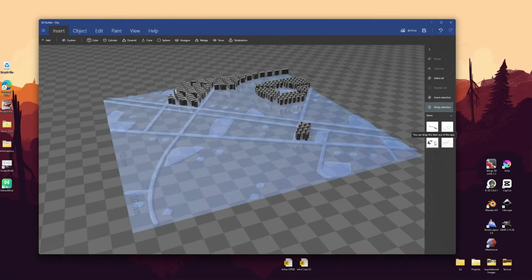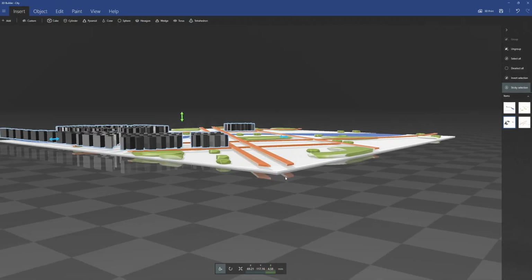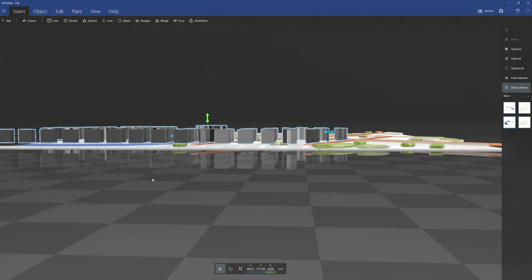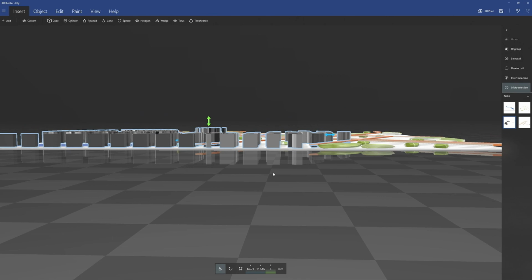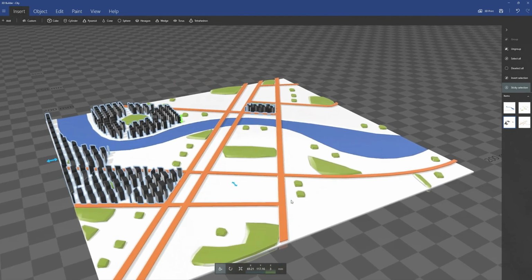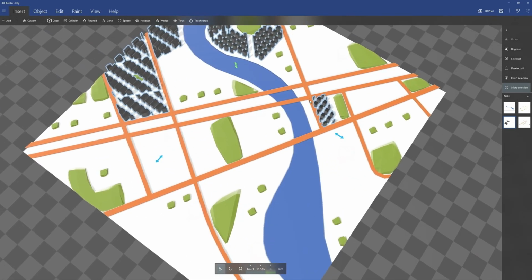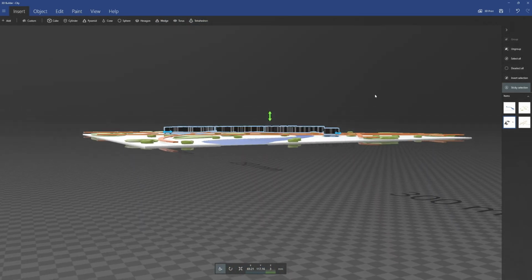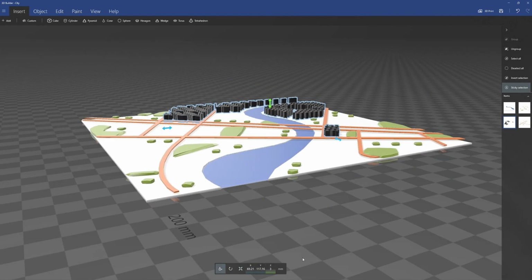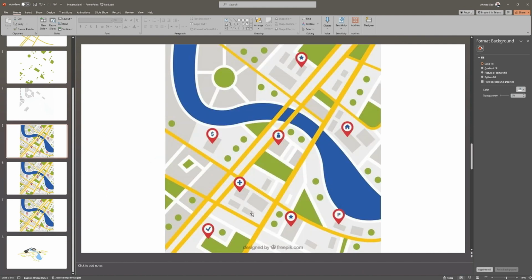Here I'm going to increase the capacity of the map by inserting some gray areas. I can also adapt the 3D building by moving it down to lie exactly on the ground to represent the exact presence. Actually, there are some crossing areas between the building and the road. We can adapt them all afterwards. I'm going to teach you how to adapt this 3D model in the 3D Builder. It's easy, by the way, not a hard thing.